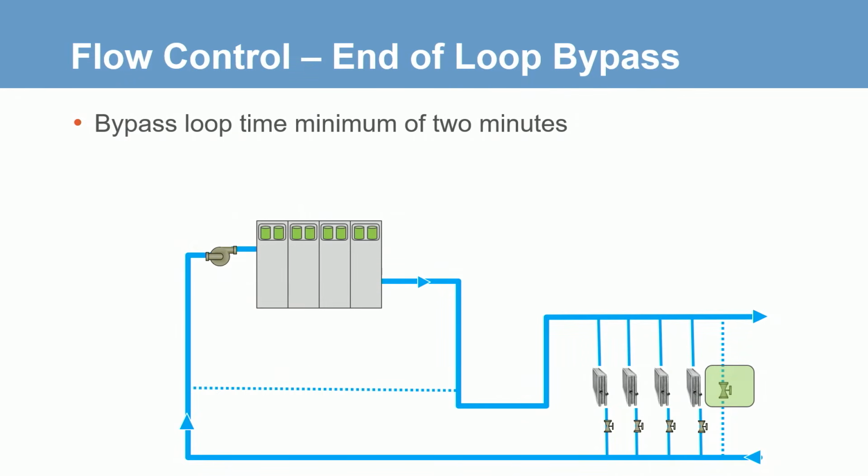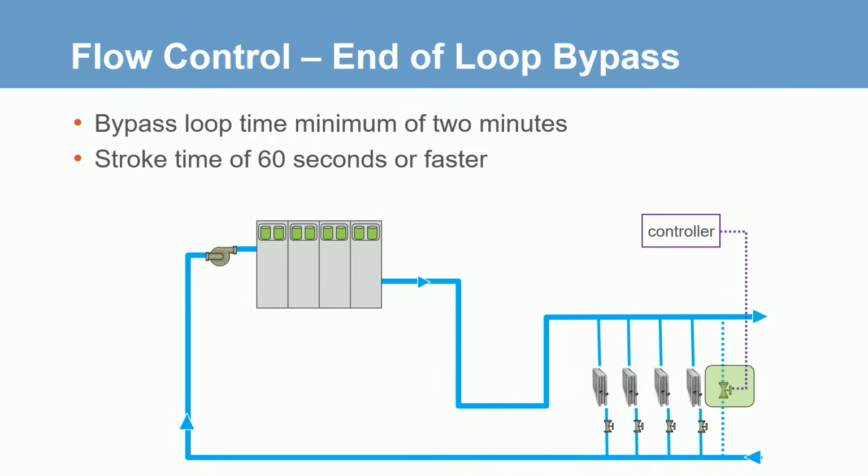The control of this valve needs to be fast-acting. It is recommended to use a direct controller for this valve instead of running the control through a BAS. This will allow for a quicker response time for the valve to open and close when needed. Last, the valve should be sized appropriately for the application. Typically, this value is around 1.5 times the design flow rate of a single module for common comfort cooling applications, though chilled water temperatures and glycol may influence this number. A critical cooling application typically would use a larger bypass.